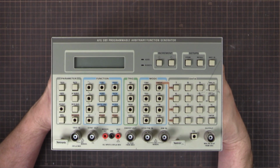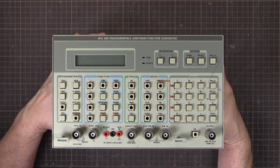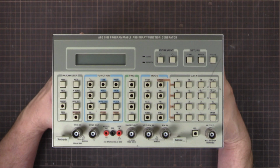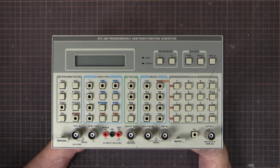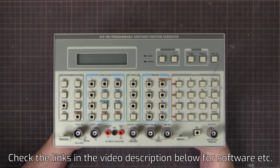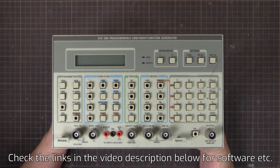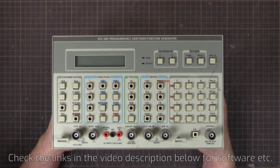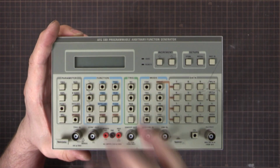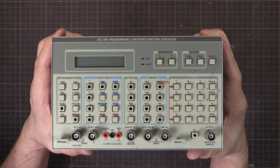I believe, I haven't looked deeply into it, but I believe the arbitrary waveforms, you can load them in via GPIB. There's no other communications on this thing, it's only GPIB, so I think I'm going to have to figure that out. Hopefully Tektronix have, or had, or somewhere is available some software that I can run on my PC to make waveforms and send it through, but if not, not sure. I'll have to research that and see what the go is. But anyway, we can get it running with the normal function generator outputs. That's not a problem at all.